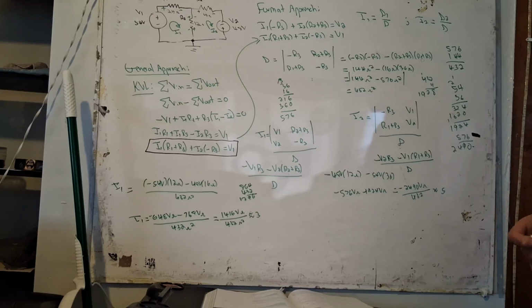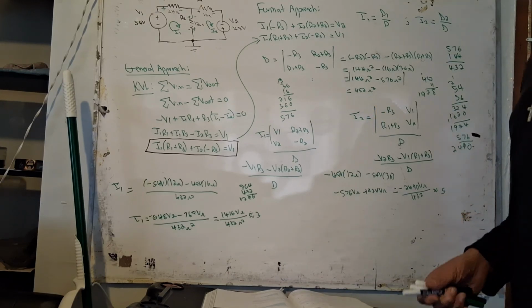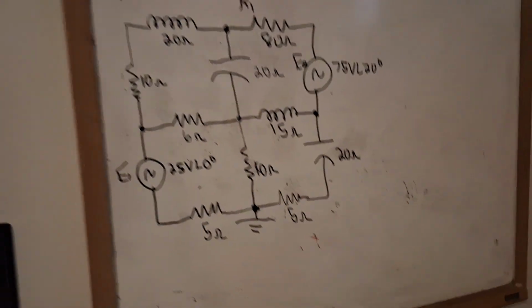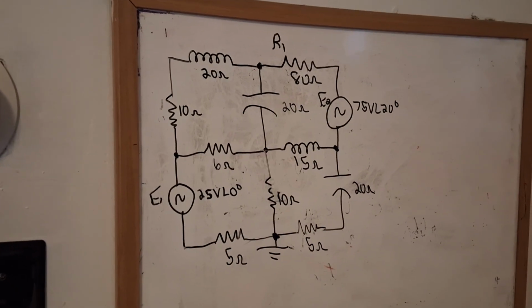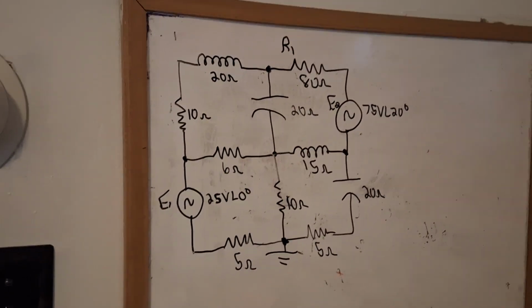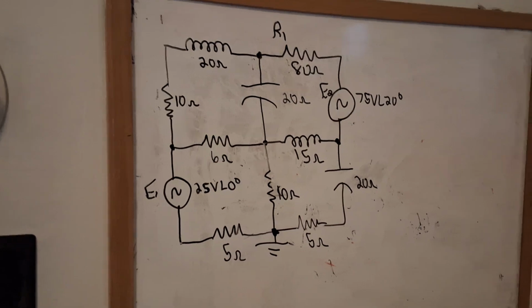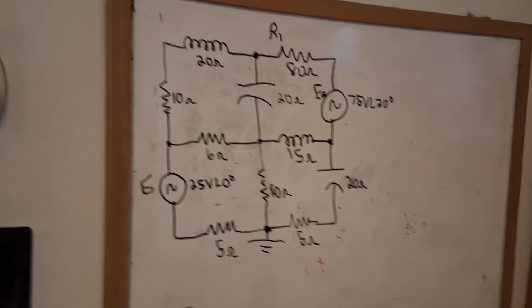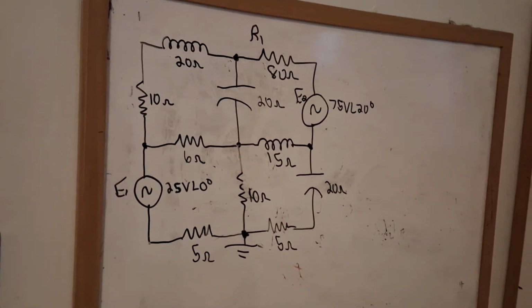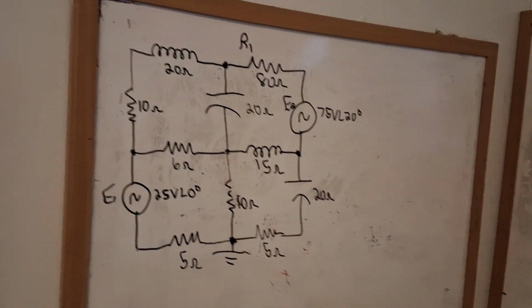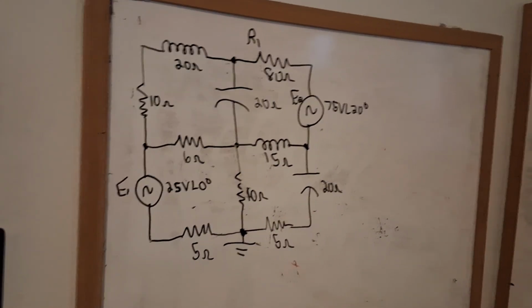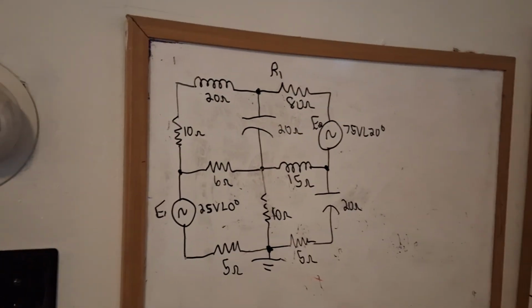And yeah, there are more complicated problems. The most complicated problem is this one right here. You can't break it down to one element. There's 2 different sources in it, and you can't use superposition, because superposition means you could break the elements down by shorting or opening the other source, depending on whether it's a DC source or current source, respectively. So that is the most complicated circuit.